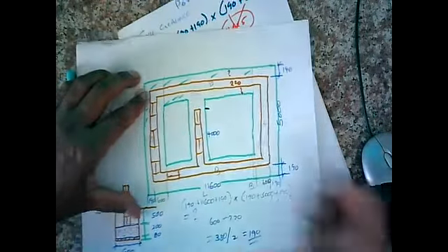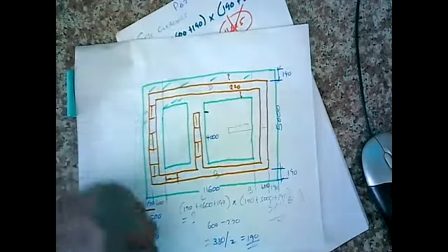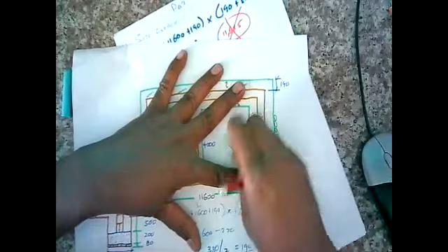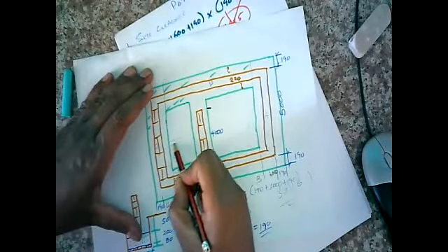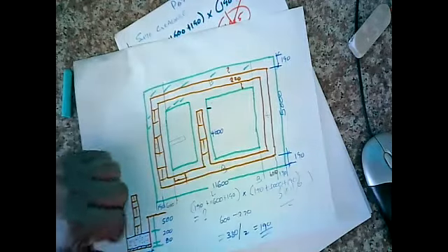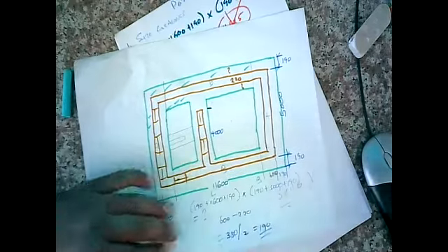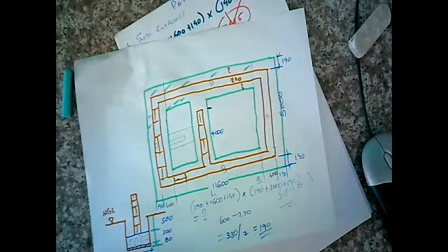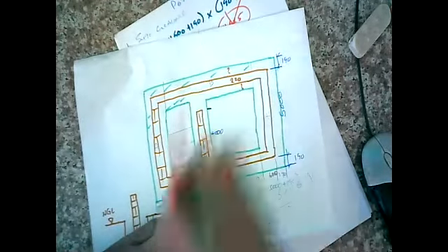If I had another wall here, if this was a toilet or something, that wouldn't be right. If there was a toilet here, and here's your doorway, I would do the same thing. My foundation would go all the way there to complete a rough foundation. So that's why I'm extending all the way to the end.